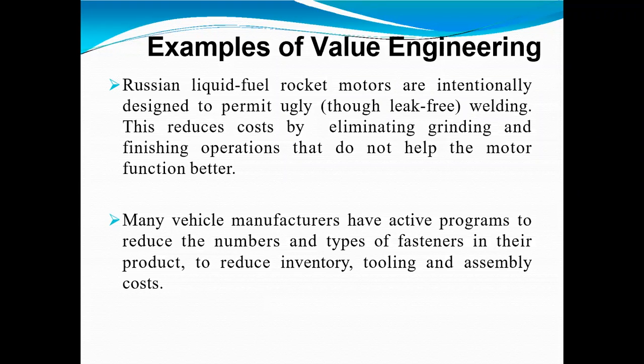Here, what is the value of that grinding and finishing? If that part goes for an aesthetic look, through grinding and finishing, there may be a chance of leakage. What they decided is, let that part look like a welded part. We will not go for finishing or grinding operations, and we will not create the chance for leaking.